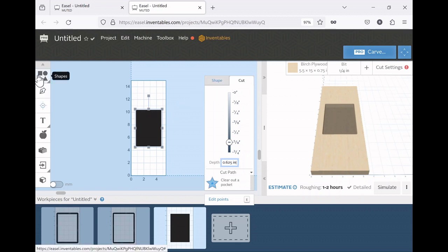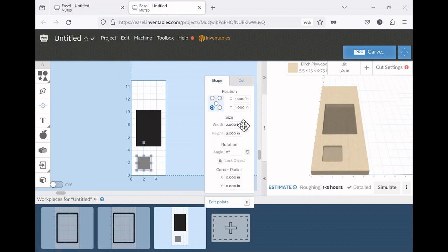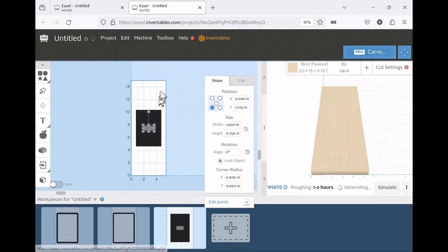All right, now we need to put the separators that we decided we need in this card box. And those separators, rectangle number 3 now, will be 1.5 inches wide, and it's going to be 3/4 of an inch high, or 0.75. I'm going to center the material, and I'm going to change the corner radius to 0.25.